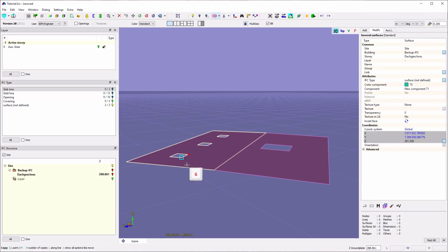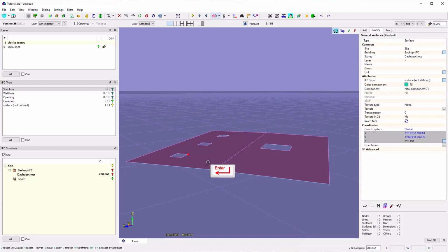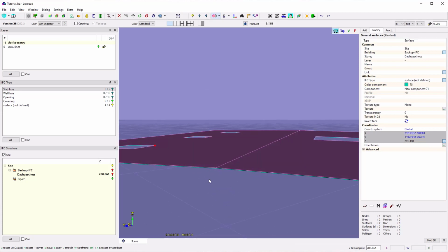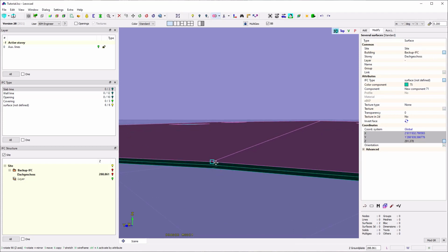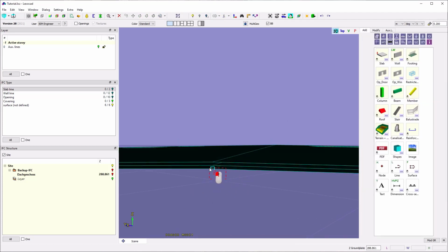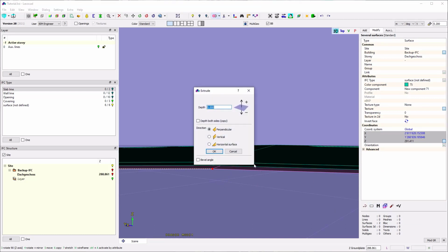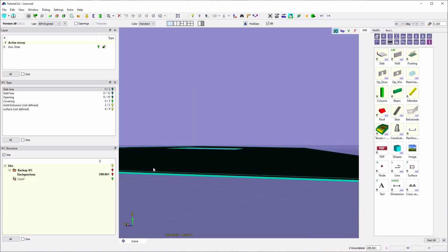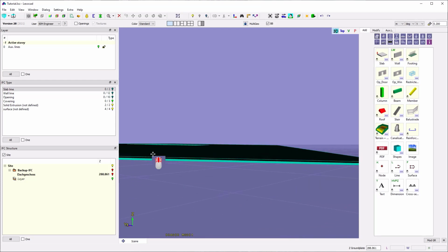I just copied that. I know my next element is 1 centimeter up, the next again, so we have these elements. As an example, I already can extrude one of them, take them both, go on extrusion, and now we see we make the depth 1 centimeter, and here we go vertical. So when we do that on the corners here, you see we have here a straight, nice vertical extrusion.